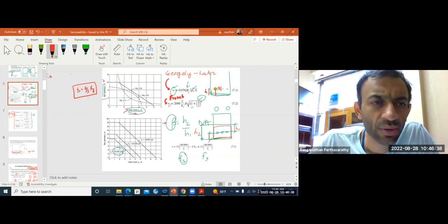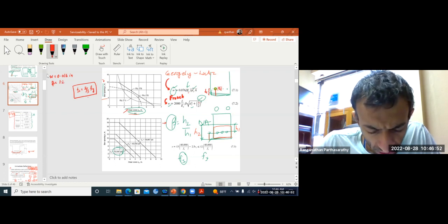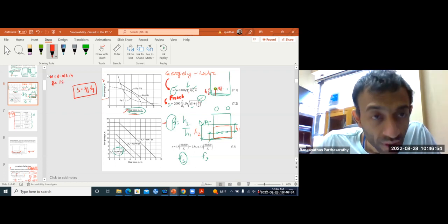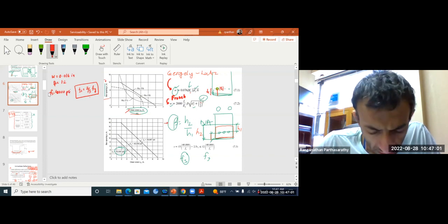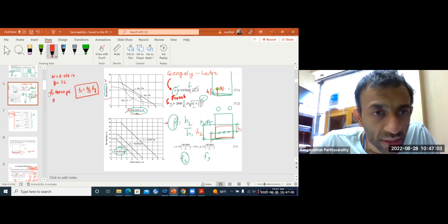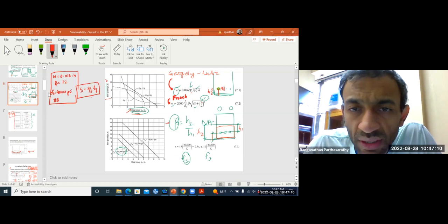When you limit your crack width to 0.016 inch, with beta of 1.2, Fs of 40,000 psi, and bar size number 8, the two equations were plotted.